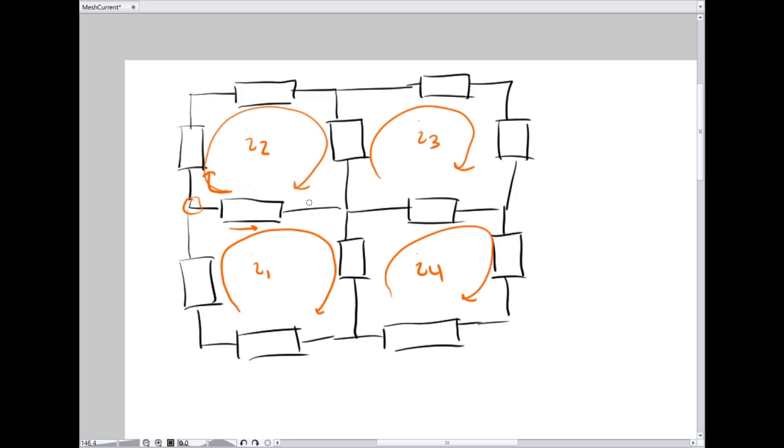And as we saw from the node voltage systematic method, satisfying Kirchhoff's current law forces the node equations to be true. And because the node equations have the same number of unknowns as equations, they, for one definition of ground, specify unique node voltages, which, with any specification of a ground, gives unique voltages across each individual component. So the solution to a resistive network is unique.